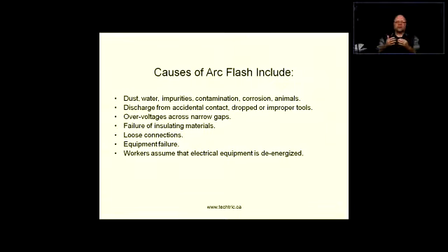We do, human flesh or animal flesh, we are conductive. Right? You can actually measure your own resistance with the ohm meter, with the digital multimeter that you have. Just make both of your fingers wet a little bit, and put your ohm meter at high range, and just squeeze as hard as you can those leads, and you're going to see some resistance on the screen.